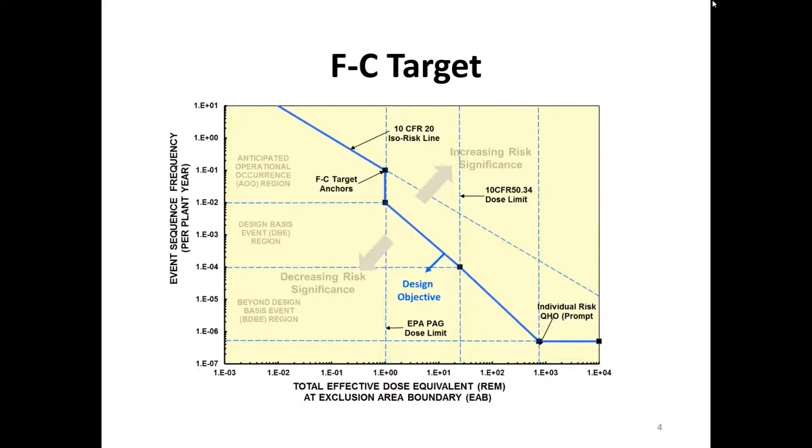in a nuclear power plant risk assessment, you look at the entire seismic hazard, from the low level to the high level. So the earthquake events that occur more frequently and less frequently, the events which we are interested in and where we do the design are in this area, the one in 10,000 and that range. So that's the event sequence frequency.